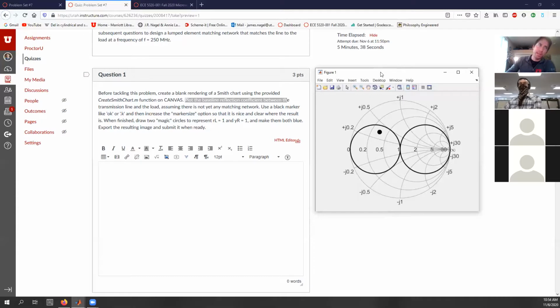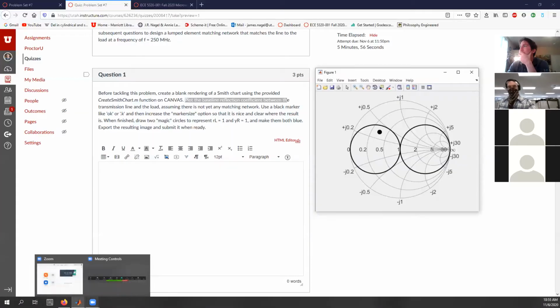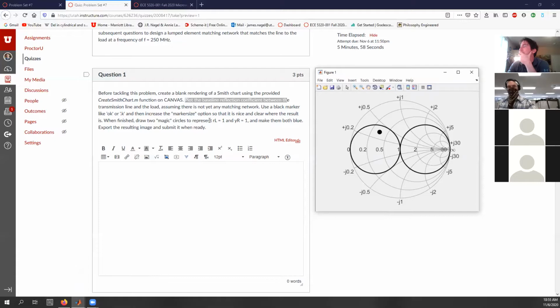Oh, that was me just parroting what Pozar said until I started working through them, and I realized that actually, if it was on the reactance circle, then you could use either. So I just assumed, I'm not looking at the capacitance circle, I just looked at the reactance circle, and that gives you the low-high.